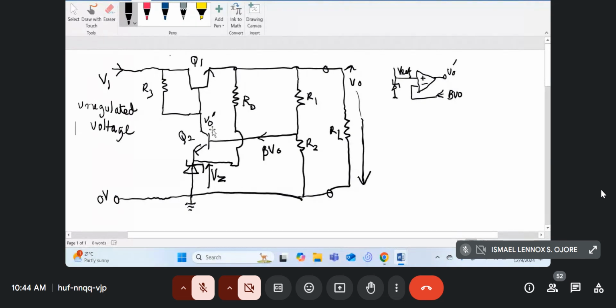Nowadays, in your flat screen color televisions, what they use most of the time is this circuit, but with an op-amp. Say that you just use those LM like the 7805, 7808, 78015. So that makes the production much quicker, because nowadays most of the printed circuit boards are made by machines which are fed automatically. So it's faster to just put one chip than to put all these components inside a board. So that's the trend nowadays. If you open your televisions, or even your laptops, and even those modern power supplies you have in the labs, they'll just have a 3-pin device which has got all of this inside. And instead of Q2 being just a single transistor, they use an integrated circuit op-amp like the ones I showed you last time.